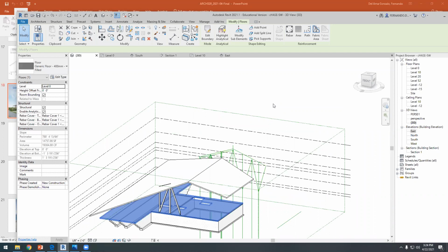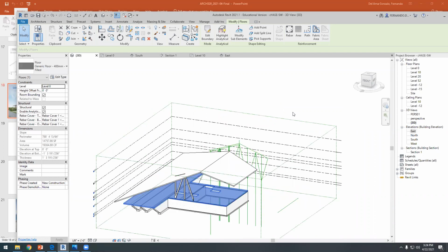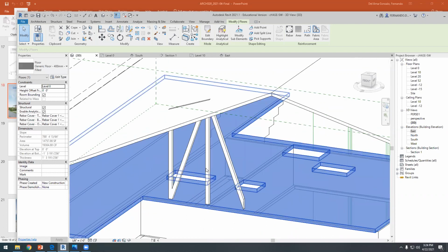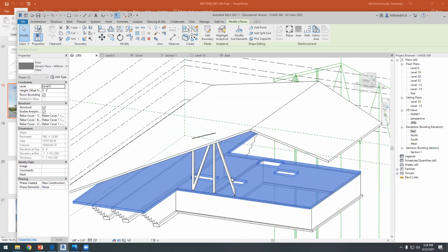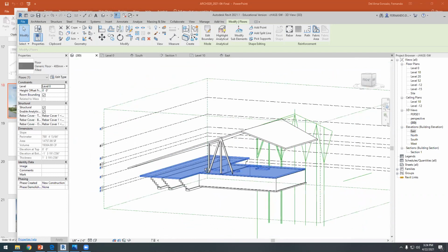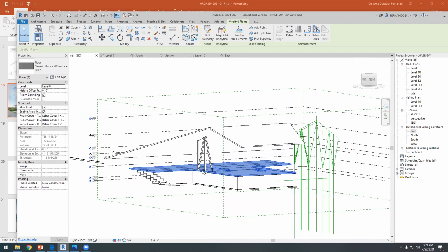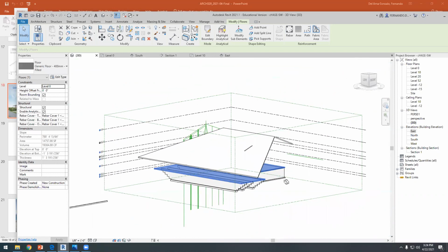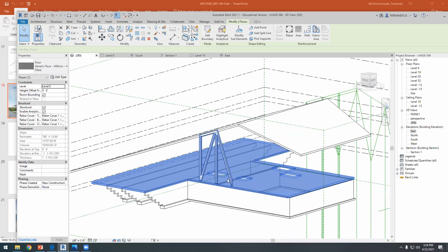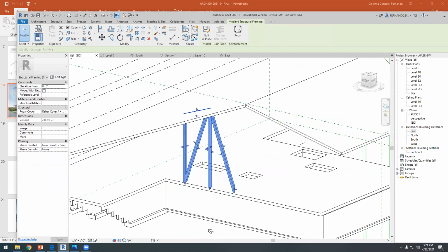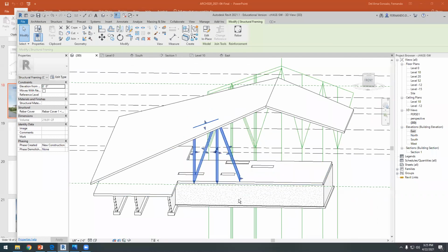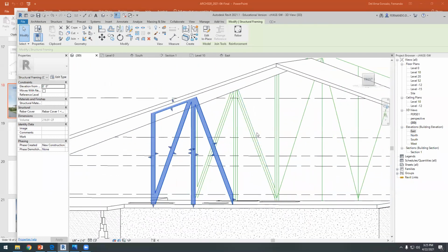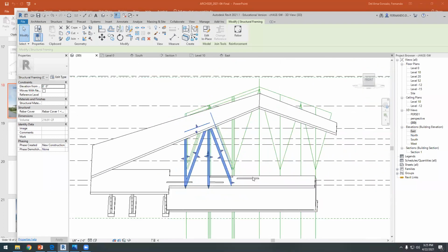In theory, the other one is better, working with a truss family, because with the truss you can calculate the structure. Here we are just modeling. We're not calculating any structure. So we can work with this option as well. It's up to you. Try both of them. I would appreciate it if I open the Revit file and I find that you have tried two different ways to do this. Probably this is easier, but you have to make sure that you are working with the right auxiliary element, and then you can create a component, and then you can do it easily.